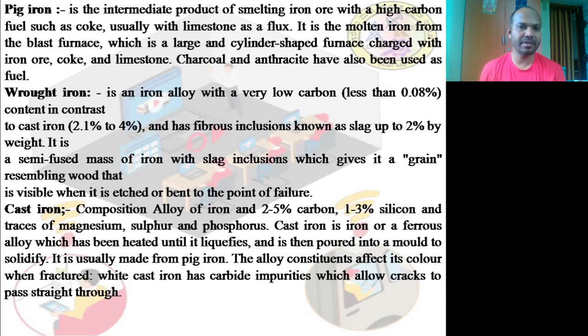In the foundries, where the material is extracted, or in the metallurgical industries, we get an ore, we heat it, and we remove the slag, and whatever liquid material remains, that is the iron. When we pour it, the molds looked like a pig shape, like a pig face. That is the reason why we call it pig iron.